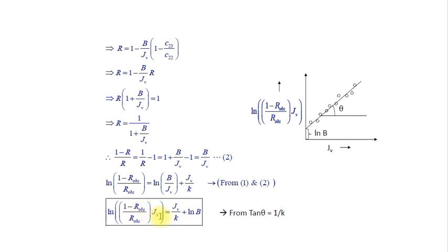JV is the total flux, that is, how much water you get on the permeate side. Suppose you are doing the experiment and you get 100 ml of water in 10 seconds, and the area of the membrane is 0.1 meter square. So 100 divided by 10, divided by 0.1, will give you the flux JV.